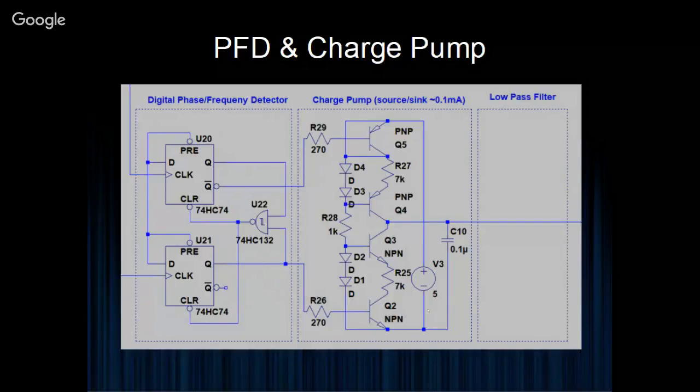Then you effectively have an integrator here, and you can source current. So if you want to drive it in one particular direction, you source current into this capacitor. As soon as that signal disappears, your capacitor should just hold the charge, right? So nothing should happen. If you wish to discharge the capacitor, you can trigger this current sink, and that will sink current out of that capacitor and linearly decrease the voltage across it.